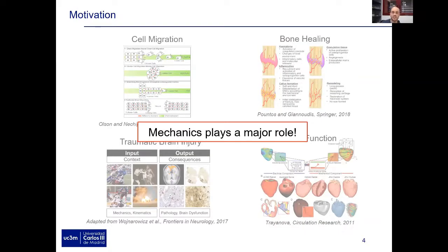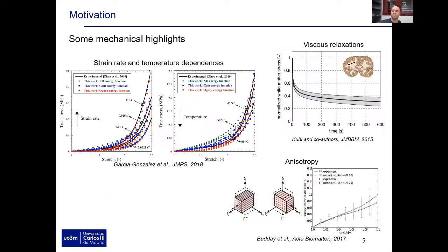And when we look inside these mechanics, we find that most of the biological experimental approaches or some of the modeling techniques assume this is quite simple, with linear elastic models following Young's modulus or even linear viscoelastic approaches. But if we look inside the dependencies of these mechanics, we realize that this is quite complex. We have many different dependencies, such as temperature modulating the stiffness of the biological tissue. Also, these biological tissues are not like elastic solids, so we have some viscous contributions.